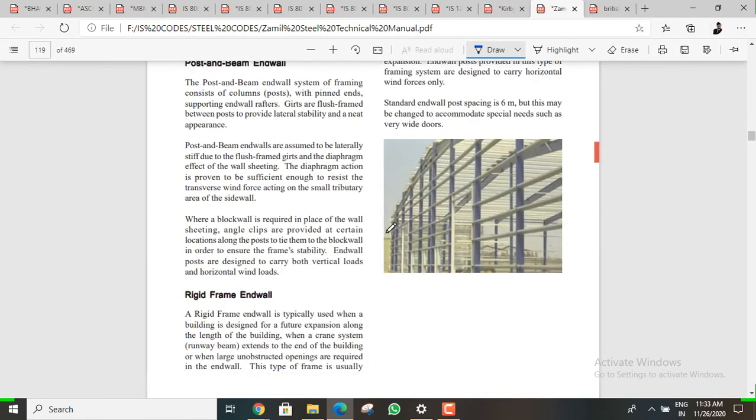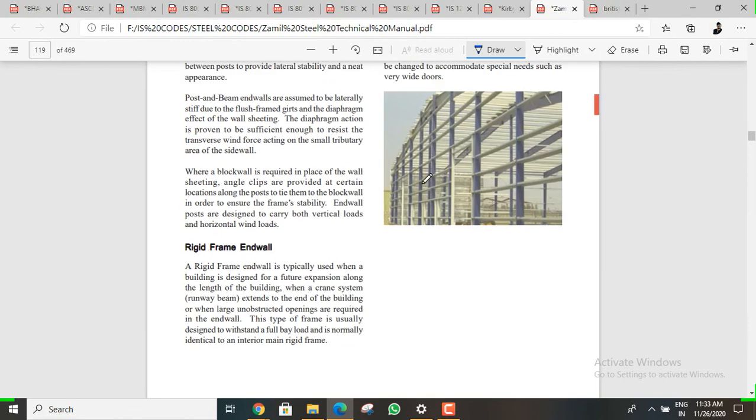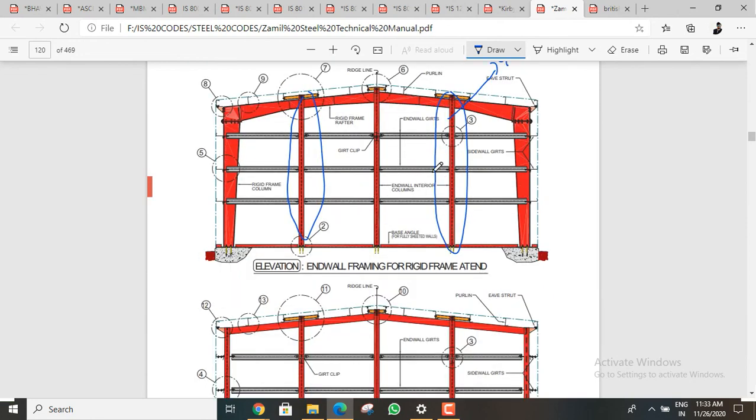So yeah, all these things we can cover. These will be gable columns, to resist the wind in the long direction. These gable columns will only be in the last bay. In the middle bays you never get any gable columns. You get gable columns on both ends. This is a hinge connection, and this will be the rafter connection and column connection.